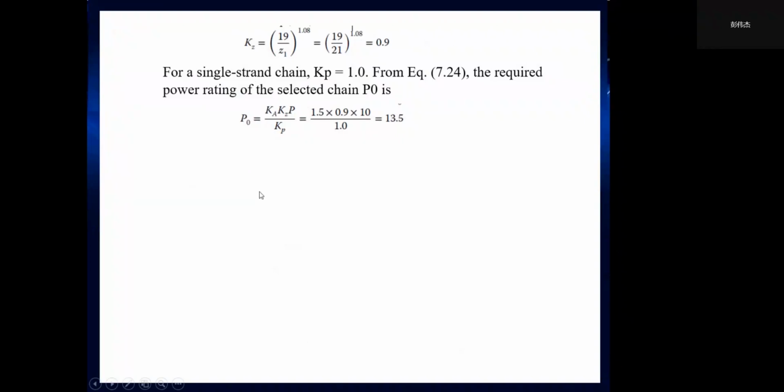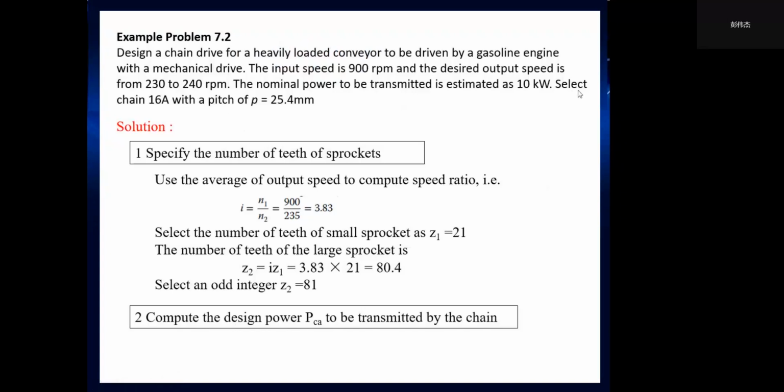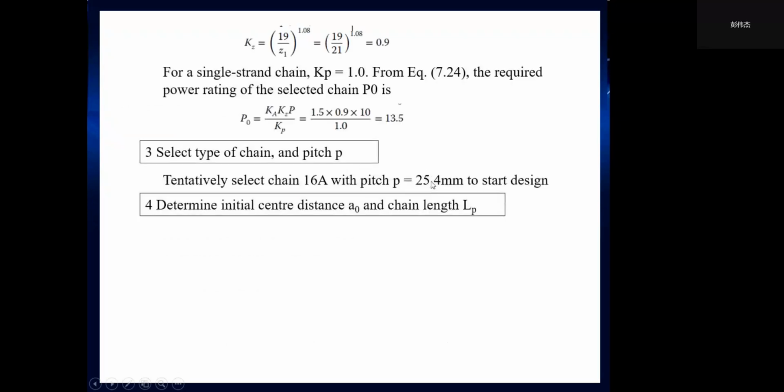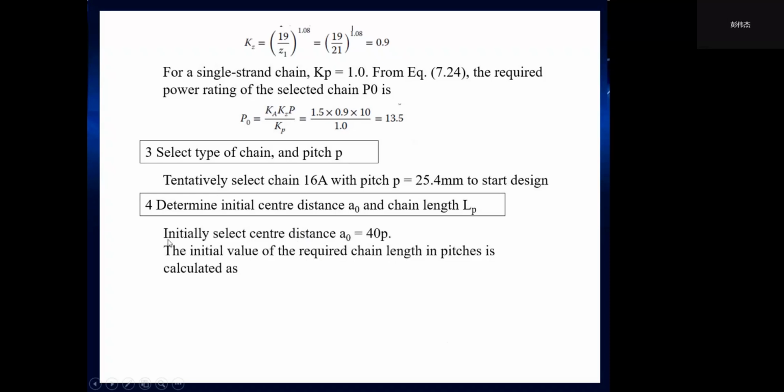Then select the chain. In this example we select chain number 16A series, and we have the pitch. Then determine the center distance.